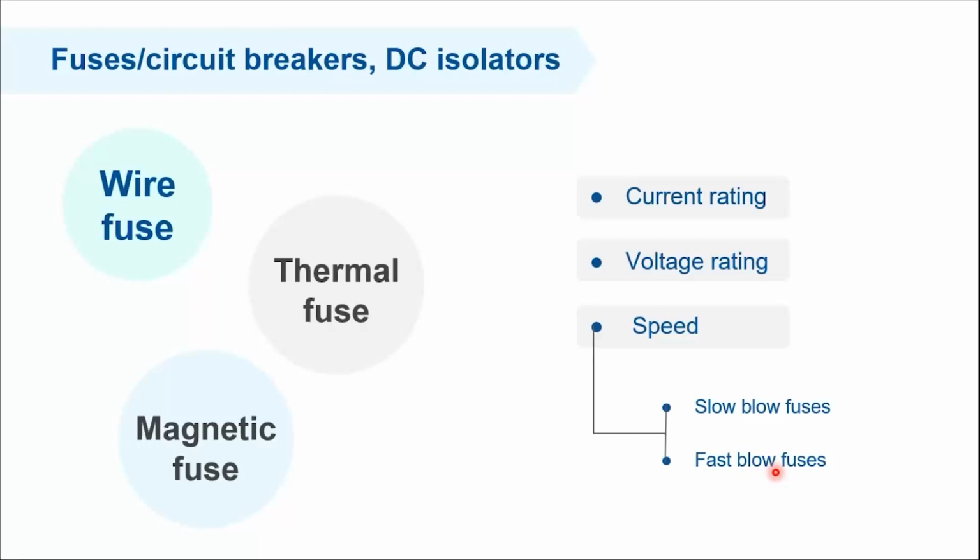Sometimes you have an AC consumer that has a high startup current, and this equipment will be something like electromotors, such as refrigerators, air conditioners or so. And in these scenarios, you need to use a slow blowing fuse for your AC part because you have such a load in your system. But in general, to make it simple and easy to understand, we use a slow blowing fuse for the DC side and fast blowing fuses or switches or circuit breakers for the AC side.